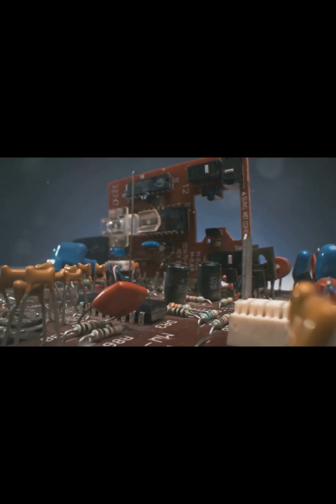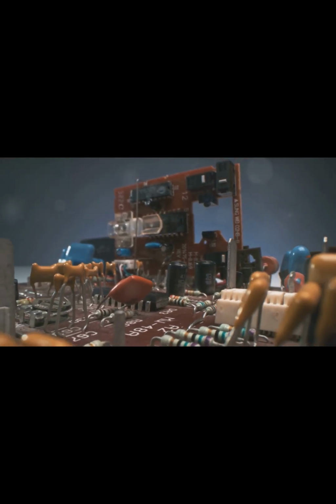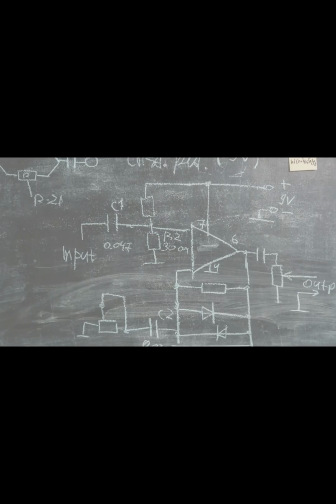Another important characteristic is the threshold voltage, which applies mainly to FETs. This is the minimum voltage that needs to be applied to the gate terminal to start turning the transistor on and allowing current to flow between the source and drain.